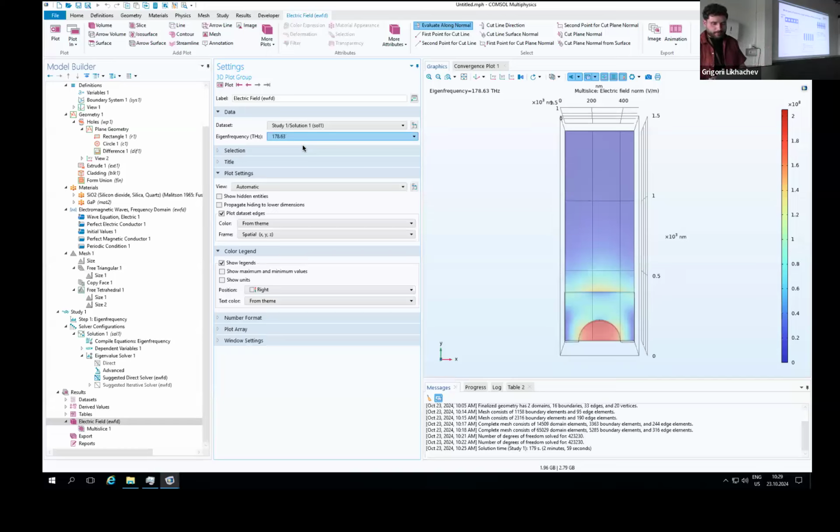All right. So, yeah. In terms of performance, are these holes better than the other? For me, yes. But if you have a good process in the clean room for your materials, then the holes are very good because they give you a nice bandgap. The question is, do you have a good quality factor? Are the losses low enough? That depends on your process and your material.